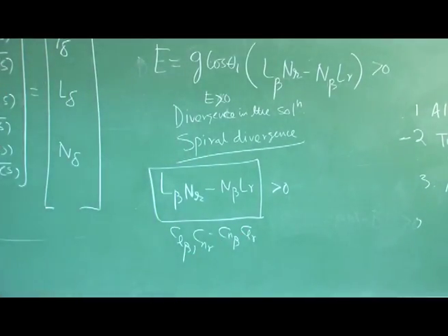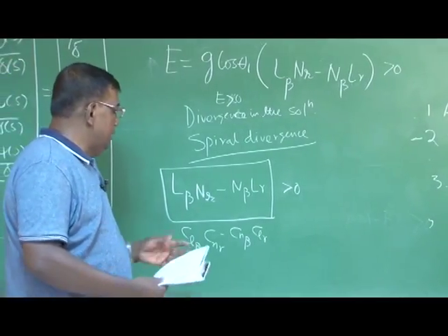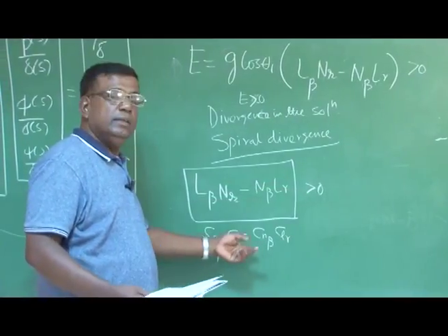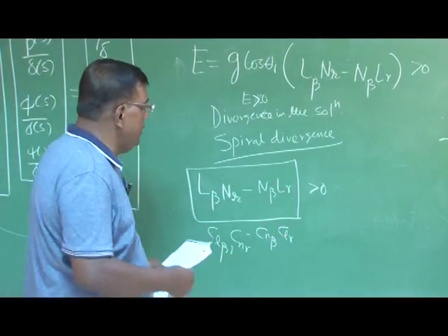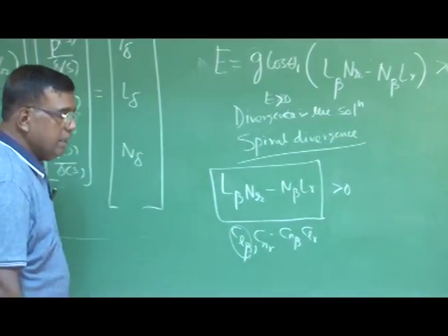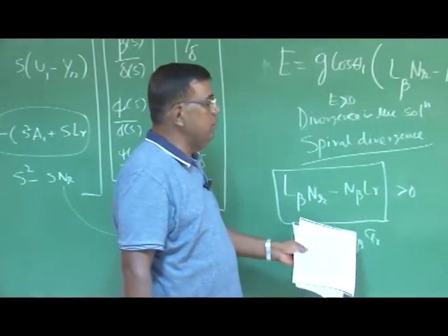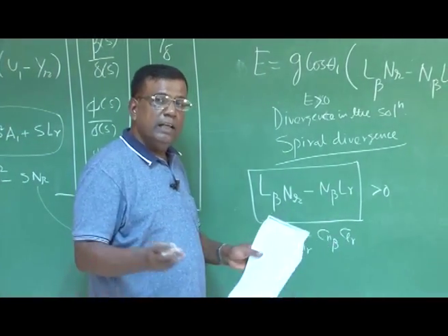These 4 derivatives are to be created in the airplane through the layout of your tail, wing, etc., such that this is satisfied. Although we talk about Cl beta for lateral stability in the static sense, it also plays an important role in dynamic stability. That is the connection.